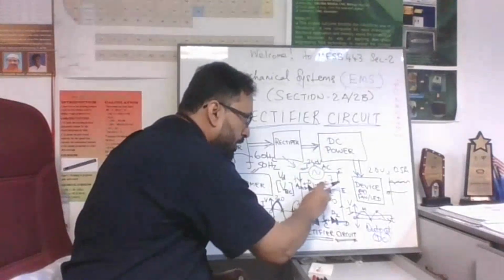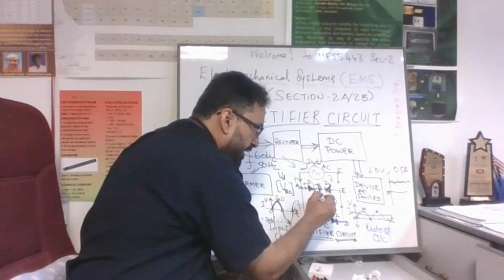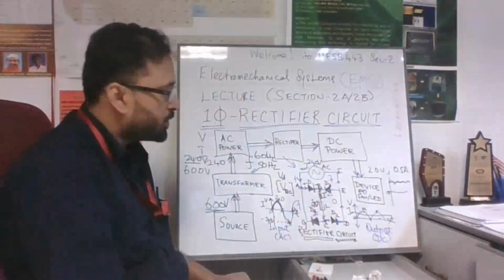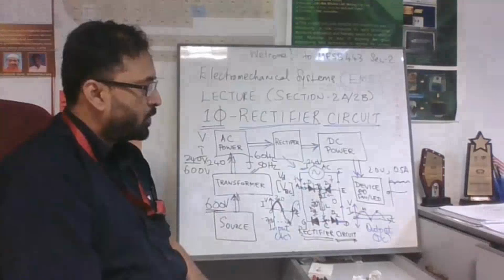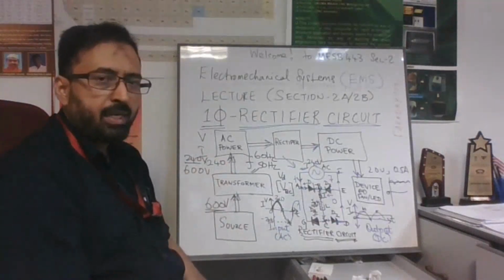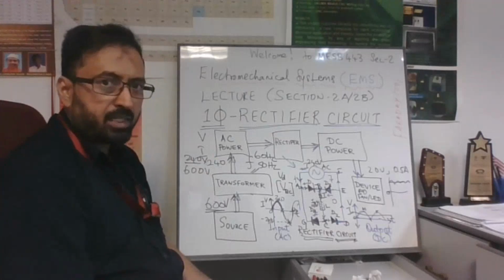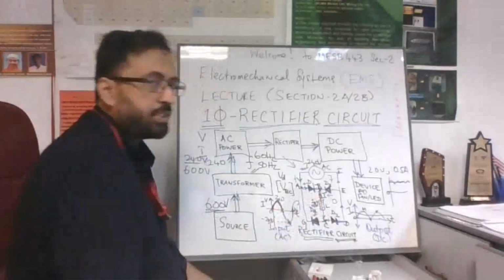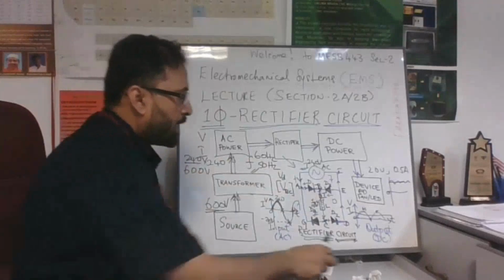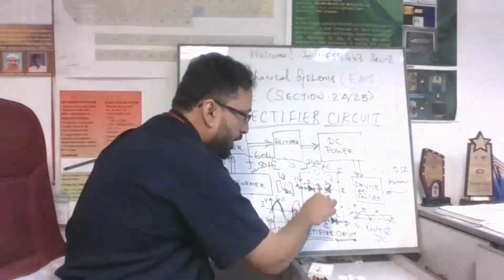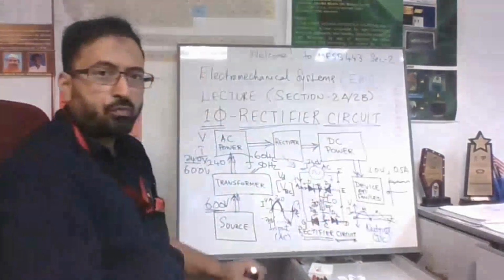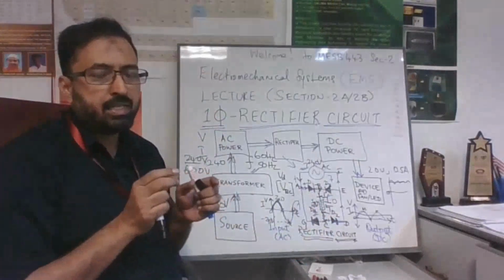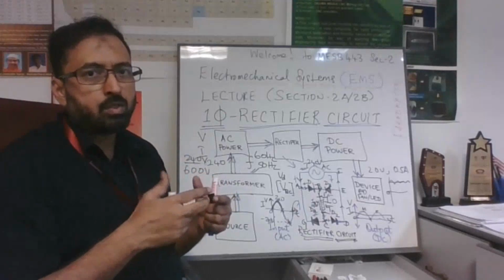Let's say, for example, you make the circuit with an inductor attached to a resistor. The resistor is the load and the inductor is the filter. We already know the principle of the inductor: when electric current passes through a coil, it exhibits magnetic energy. So the magnetic energy is built into the circuit, and you can utilize this energy to stabilize the output power. As another example, instead of the inductor, you can have a capacitor. If you attach the capacitor in parallel to the resistor, the function of the capacitor is to store electrical charges and then deliver them into the output circuit in order to stabilize the output.